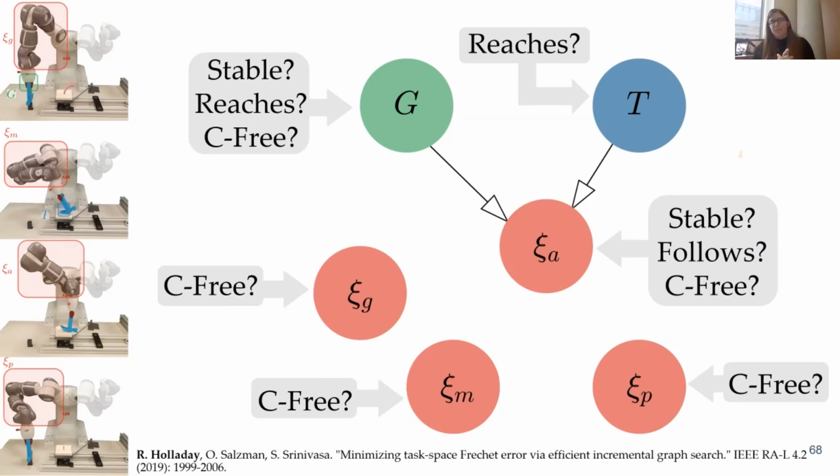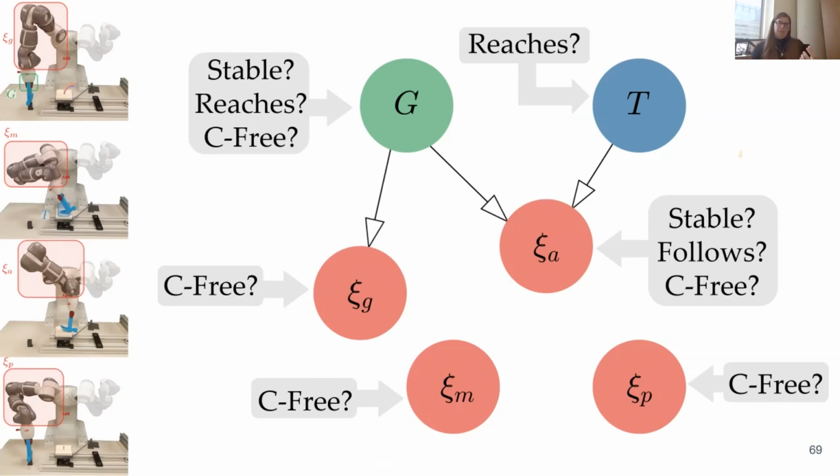So we use a special planner for that. Otherwise, once we have our grasp, we can now solve for our path to the grasp. For anything besides path following, it's not terribly important, but we use a bidirectional RRT for generic collision-free planning. Essentially, once we have these variables figured out, we have enough information to solve for all of the connecting pieces.